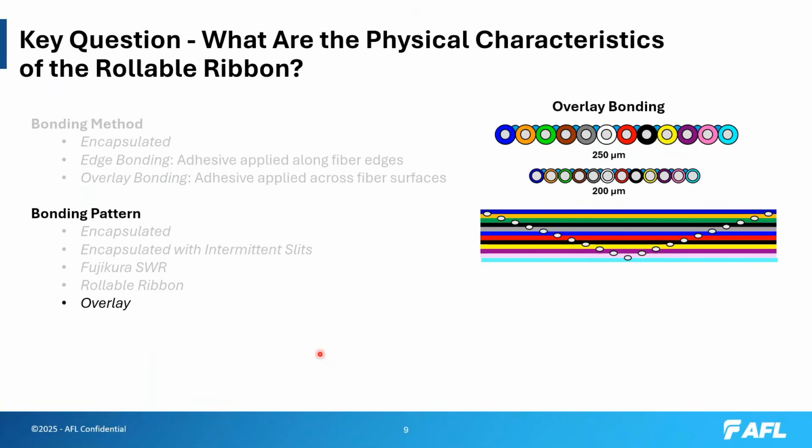Going from 200 to 250, if you keep it at 200, use the 200 micron fiber holders, 200 micron V grooves, you should have a fairly good success. The only negative to this is since that material is riding up on top of the ribbon, you don't want to lay the bonding on the bottom of your fiber holder, meaning you don't want that flipped over 180 degrees and clamp with the bonding laying in the channel, the surface of the fiber holder.